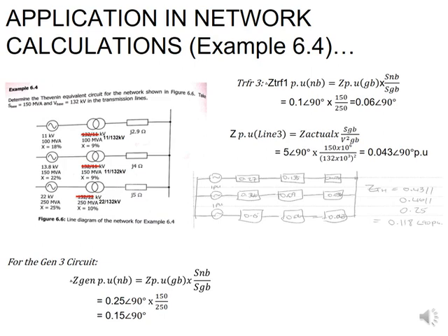Because they say a Thevenin equivalent, you can also add all those impedances together and make them parallel to one another, and you would end up with an equivalent Thevenin impedance of 0.118 at 90 degrees.